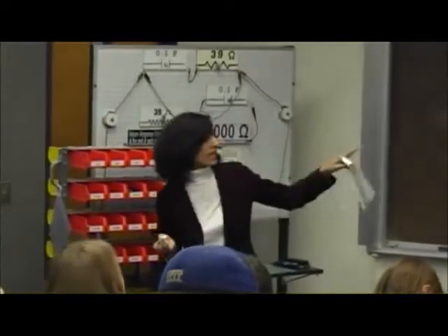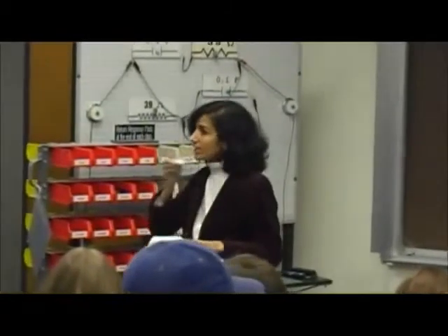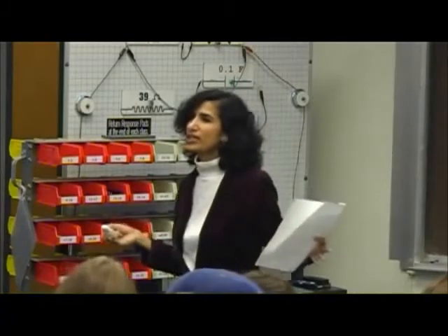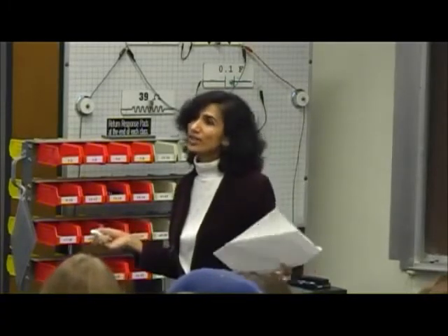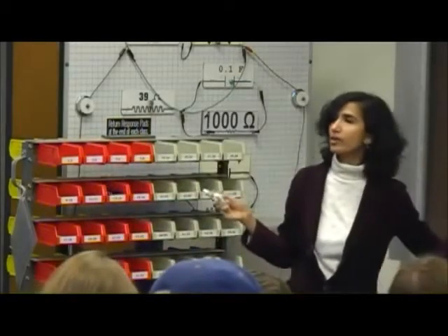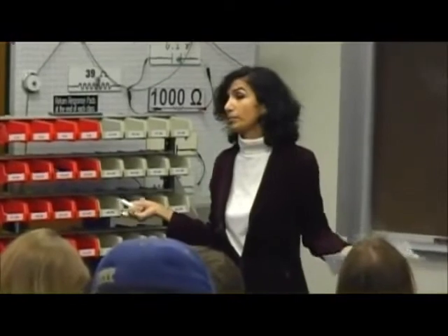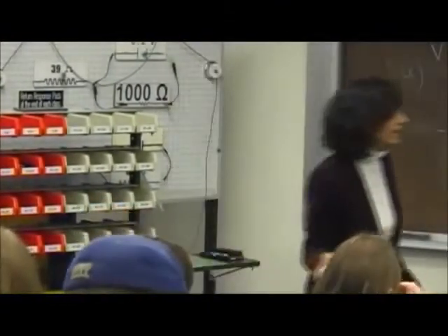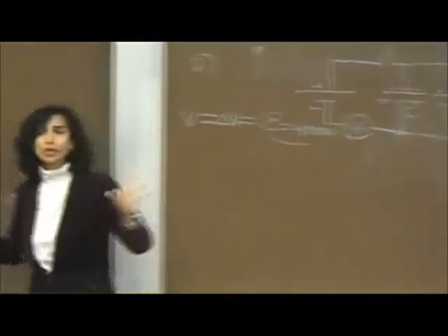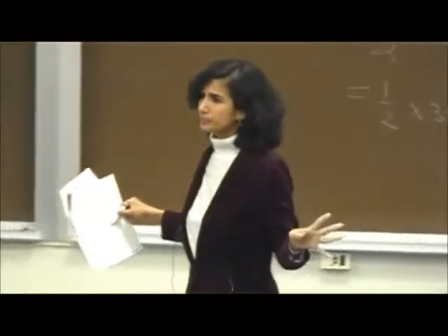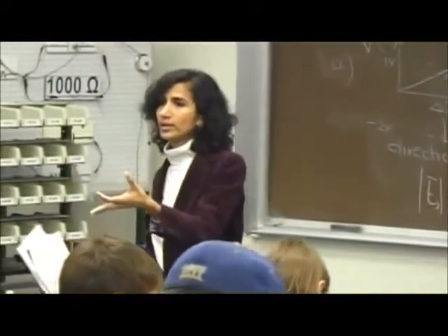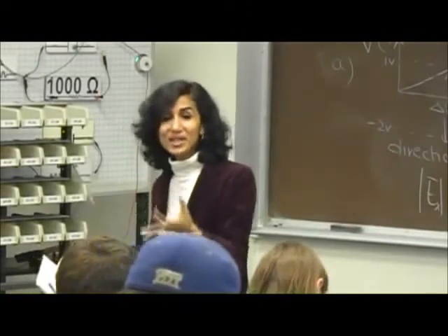But I just wrote script E because sometimes you will see that notation in the book, and I want you to be used to it. It really just means EMF of the battery, which is really the potential difference across its terminal. For an ideal battery, EMF is really just the voltage of the battery. But otherwise, if it's not an ideal battery, then EMF should be thought of as the potential difference when you have not connected it in a circuit. So if you take a 3-volt battery, its EMF is 3 volt. If you take a 6-volt battery, its EMF is 6 volt.